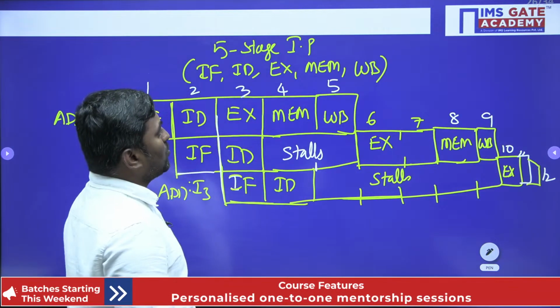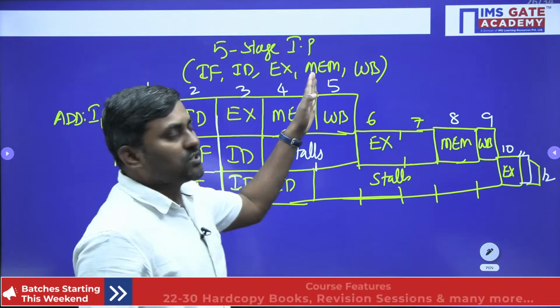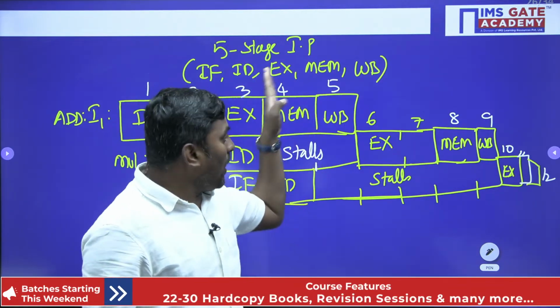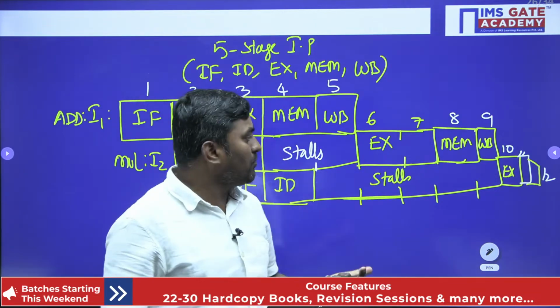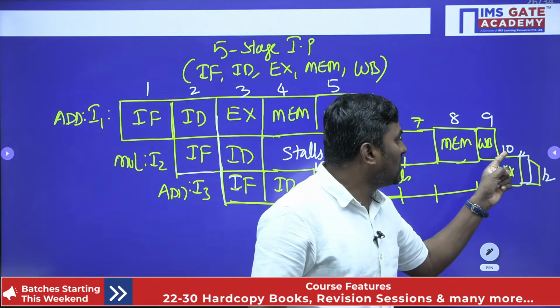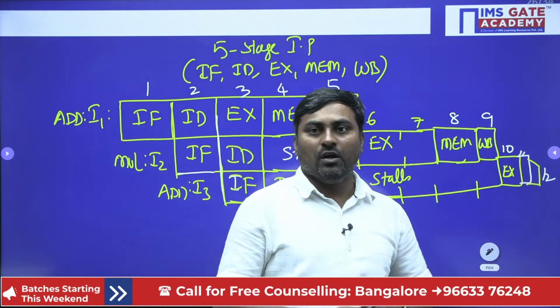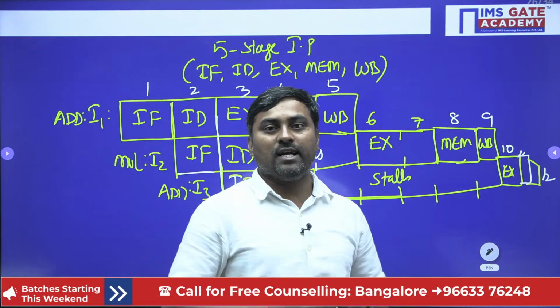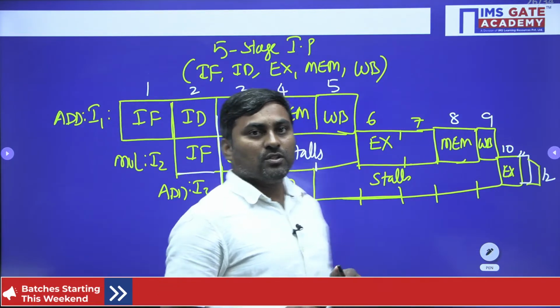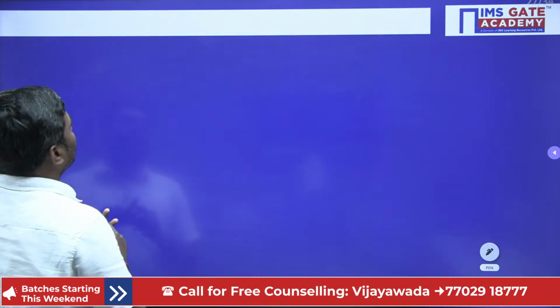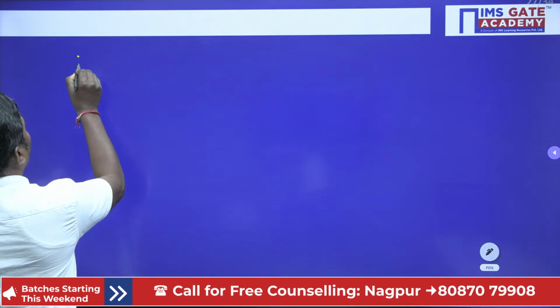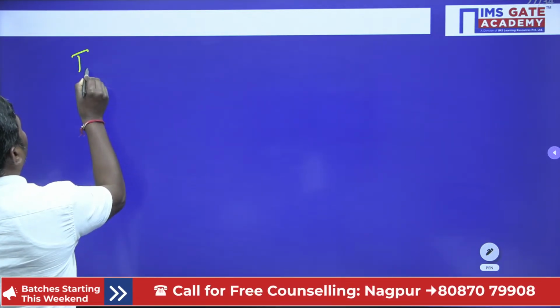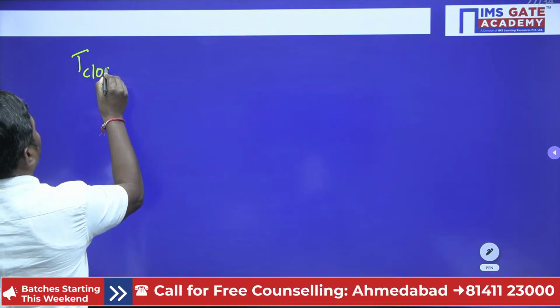So the 12th clock. What is the observation? The first instruction takes 5 clocks. After that, multiplication takes an extra 4 clocks. After that we run addition, which takes an extra 3 clocks: 10, 11, 12. Now is it required to draw the entire timing diagram? Can I generalize or not? Observe the generalization. Now I am marking the number of clocks here.